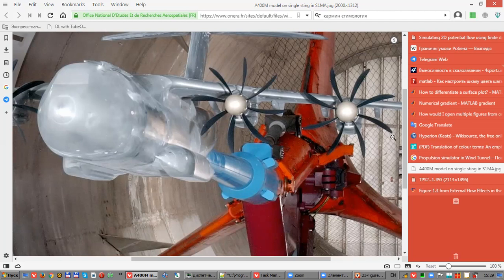And creation of a measurement system is a very costly and very elaborate task. When you have a working device, there is no necessity to change it to another type. When you develop a new wind tunnel, you need to select the better device. But when you have a working wind tunnel, you don't need to change the working device to another type, because calibrating all these sensors is a very elaborate task.